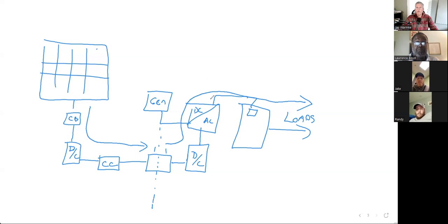Now, how do I size the inverter? How do I decide what size inverter I need? It has to match, it goes off your load. Right, but the load is not the daily load. The daily load would be in watt-hours per day. What I'm worried about is the maximum power draw